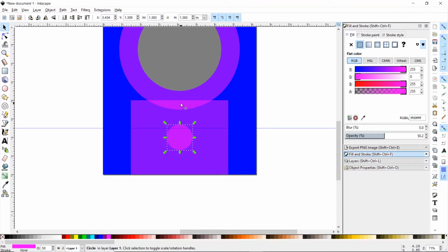And now I want to move it straight up, so I'm going to press Control, which is going to lock it in whatever direction I start moving, so it won't be a little off to the left or a little off to the right. So if I hold Control and start dragging it, you can see even if I move my mouse left and right, it's not moving left and right. Now if I move back closer to where I started and start off moving left or right, same thing happens. Now it won't let me move up and down.